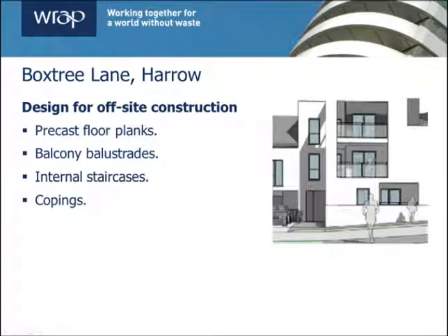The architects at Box Tree Lane also managed to design out waste by using the second principle, designing for off-site construction. All the floor planks in the development were precast off-site, which was more resource efficient and reduced site waste. The balcony balustrades were not only manufactured off-site, but also finished off-site, thereby reducing the number of trades on-site for this element, which granted did not result in a huge waste saving, but was seen as an easy win.